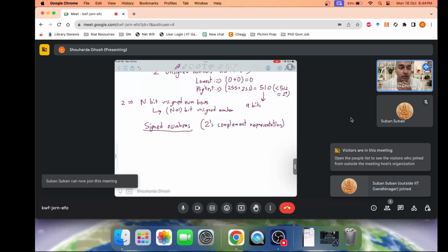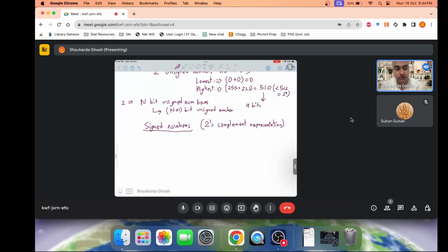If you do addition of two signed numbers without 2's complement, using some other representation such as the signed representation or one's complement, then the adder will require extra logic circuits for decoding which is positive, which is negative, which is greater, which is lesser. But 2's complement does not require any of these things. If both numbers are in 2's complement, you can use the same hardware for addition of positive, negative and mixed numbers.